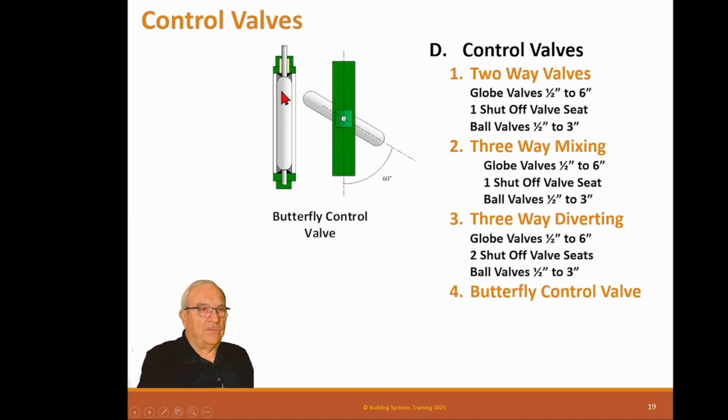Now, butterfly valves have this wafer in this frame, and what the deal is, this 60 degrees is telling you that between 60 degrees and 90 degrees full open, no control. Nothing happens. It all happens between 60 degrees and closed. So when we're doing a butterfly valve and trying to use it for control, mostly these are shut-off valves. You're trying to use a control, we only control to this 60-degree angle. Because if you try to control the 90 degree, you just lost 30% of the action of that valve. So you need to make 60% full open.